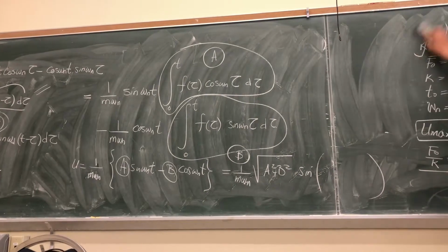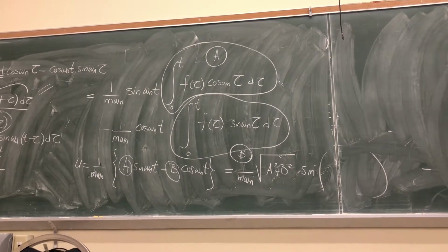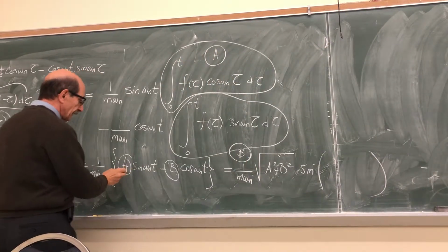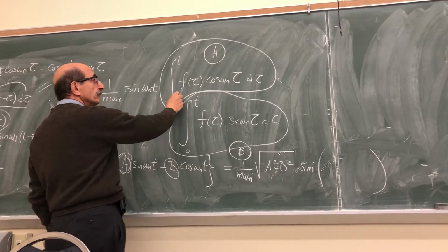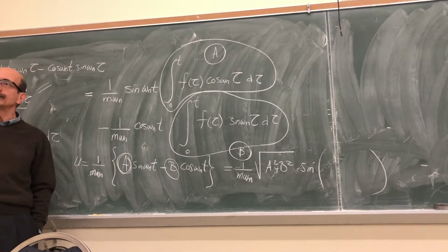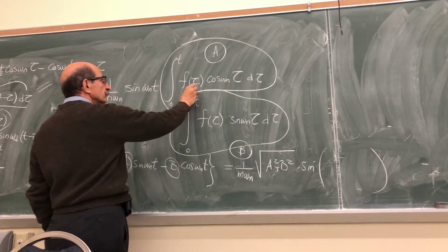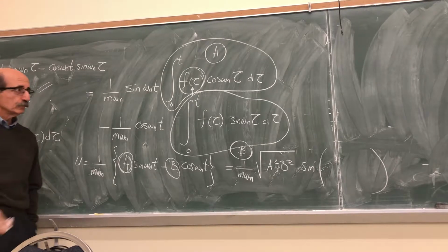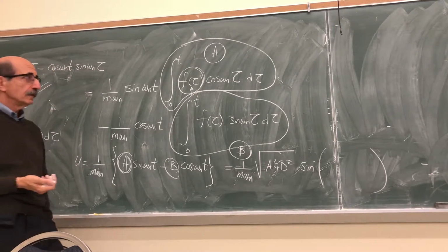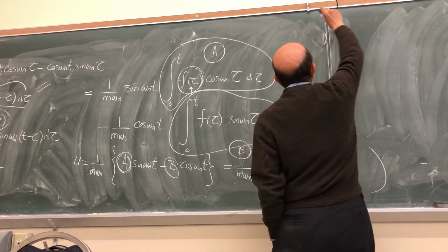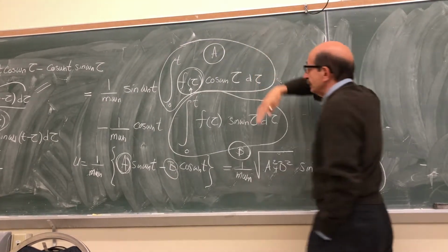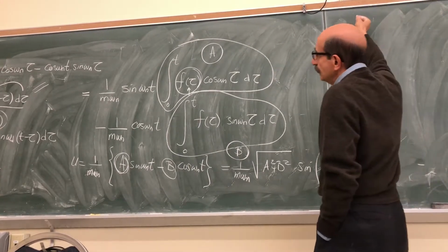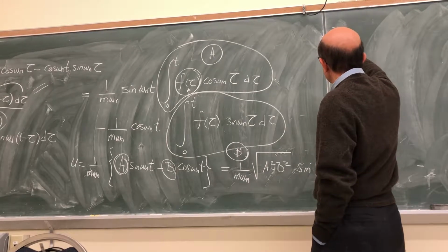the Duhamel integral. Because all you have to do is perform these integrations. In other words, find A and B. Of course, it's not easy because it depends on this function F of t, which can be discontinuous, can be of all kinds of shapes. So there are procedures to do that. We call those numerical integration procedures that maybe someday you come across if you have taken a course, maybe finite element. There are some numerical analysis approaches.